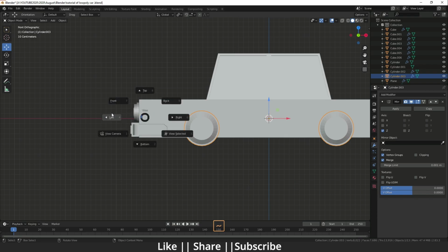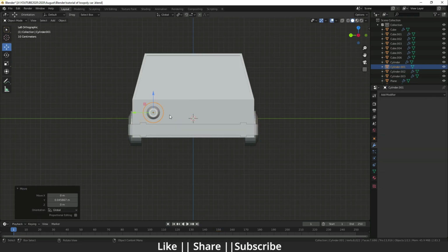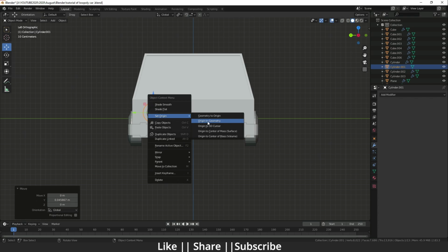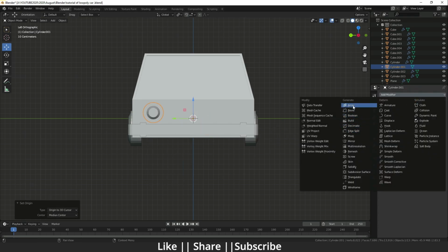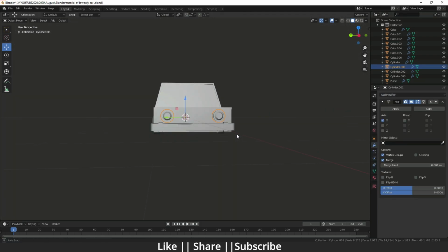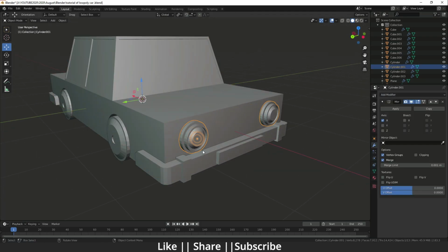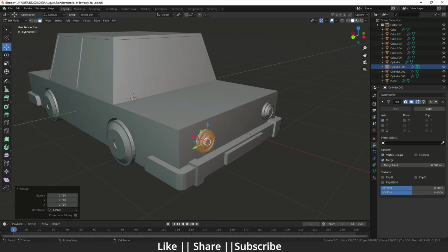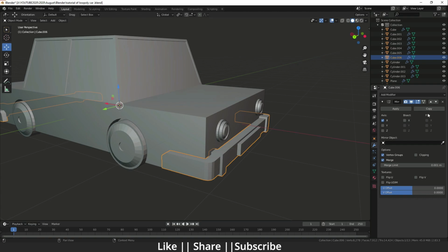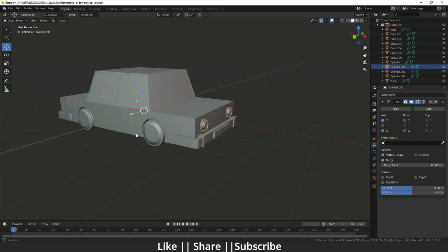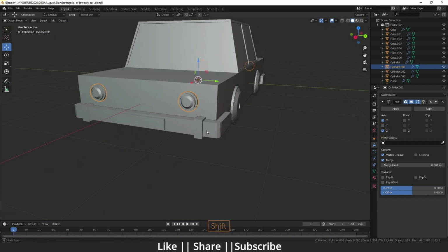So I'm just going to use the mirror modifier like that, and I'm just going to scale it a little bit like that, and the same I will do, I'm just going to select and press Z, so it will apply here as well.